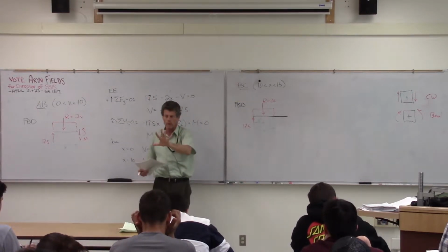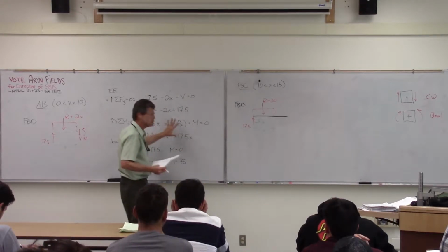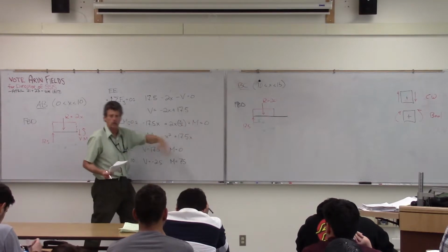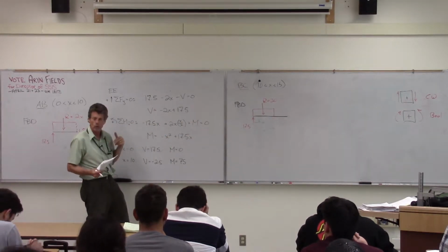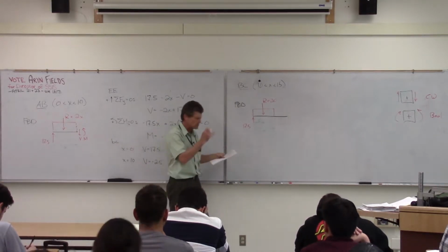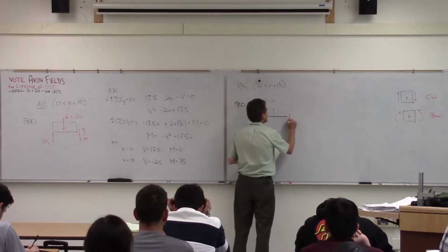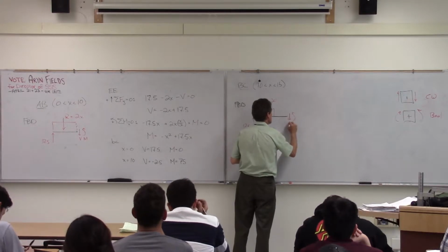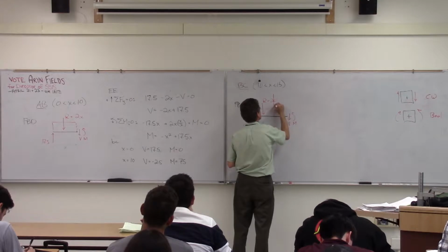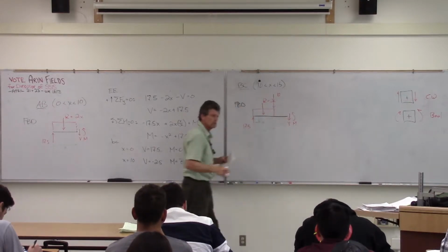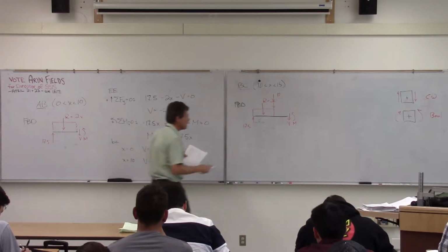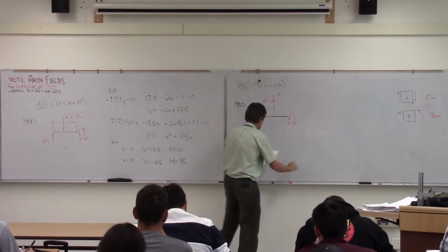And it's going to be important because when we start doing these equations, we can't be using this equation for 15 or 20. It's only valid between 0 and 10. This one's only going to be valid between 10 and 15. So that's the key thing I'm trying to indicate there. Okay, so we got our shear and our moment. And then the other thing we've got here, I forgot to put on there, is that 10 kip load. So we got that concentrated load. So all of a sudden it shows up, and I'm going to have to account for that now in terms of my equilibrium equations.